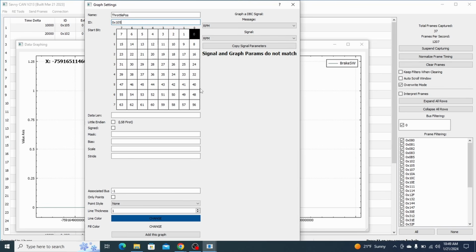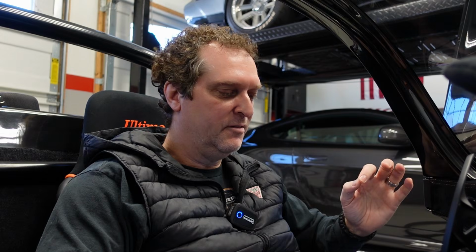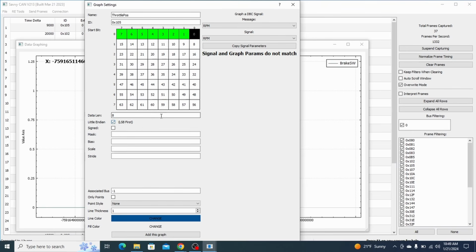This time we were looking at byte number 6, but the length was 8 bits. It was the full 8 bits, remember? So I'm going to put in 8 for my bit length, and you'll notice my chart up here changes to tell me which bits we're telling this software to read. We're little endian. You can see that impact. That's the other thing. You can play with this. If you're trying to get your mind around what little endian and big endian is, you could just simply use this. Put in your start bit position, check the box, and you can see what happens.